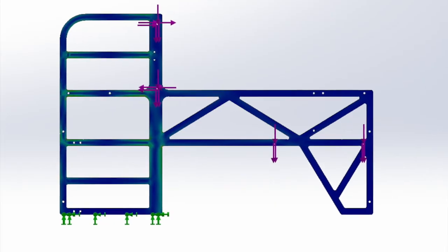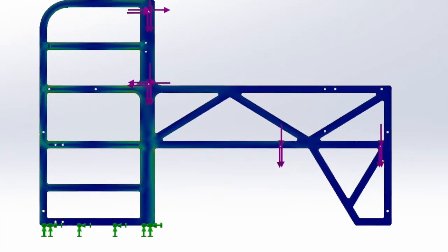We designed thruster guards, and when designing these thruster guards, we hit the guards with mallets to test them. We compared breakage locations to finite element analysis in CAD. And in that way, we were able to very quickly iterate the design until we had good thruster guards.